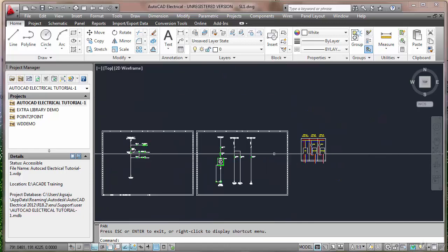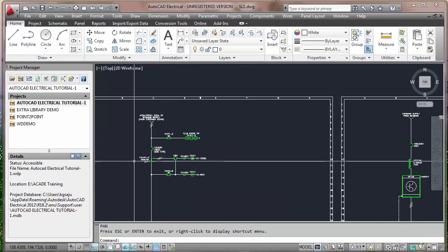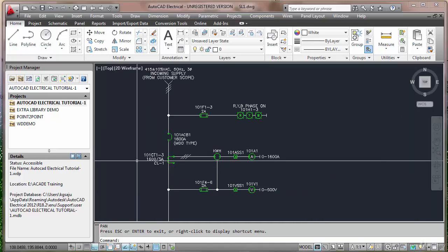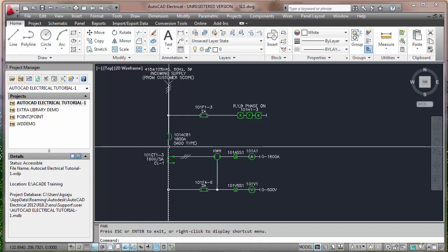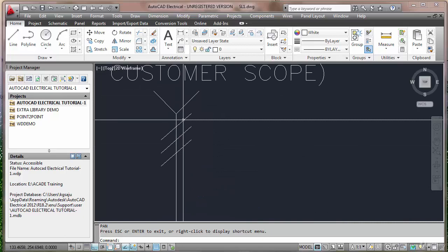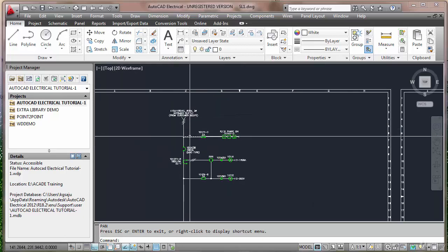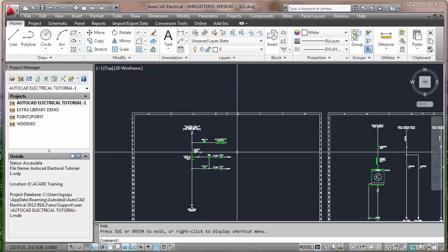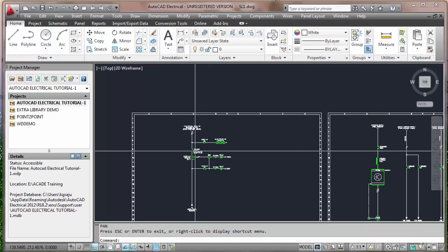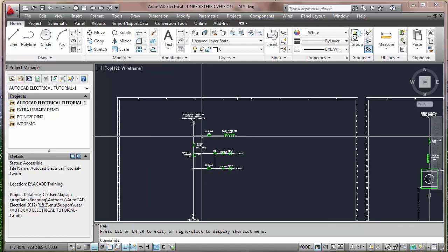Now what I am going to do is, I will show you how I draw the detailed wiring diagram. This is a simple single line diagram. You cannot put any wire number here because you can see only one line here. In fact, there are three phases coming. This three line represents three phases coming here, and you have to put some wire numbers there, and there are many controls. You cannot represent all this through a single line diagram. This will give you the overall idea of what a circuit looks like.